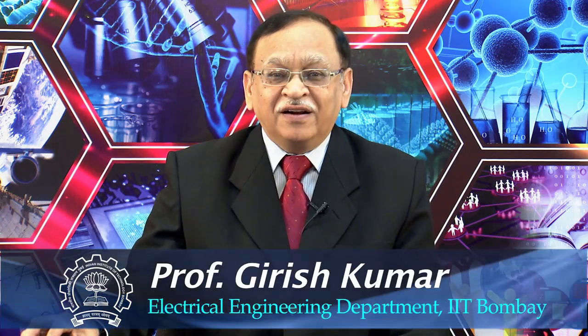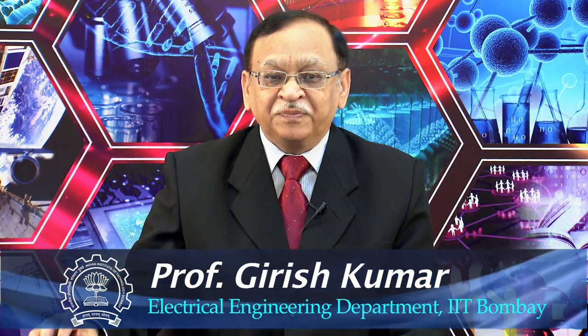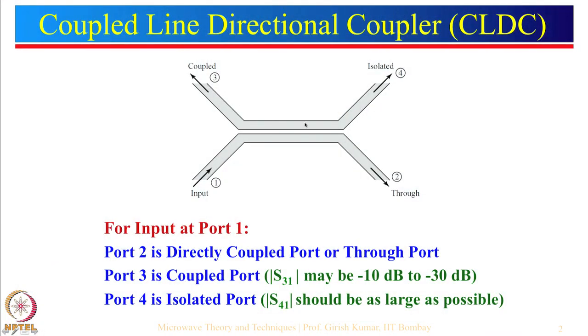Hello. In the previous lecture, we talked about the coupled line directional coupler, where there is an input from port number 1 which goes directly to port 2. If you put another line close to this particular line, then because of the current flowing in this direction, the induced EMF is in this direction. So, this becomes the coupled port and this is the isolated port.